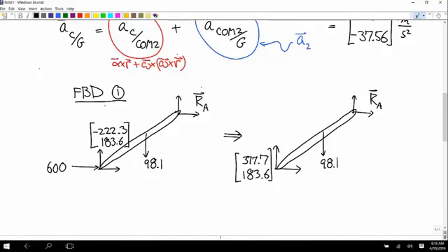I'm not going to do it, but how would you calculate RA if so? Why don't we know that, first of all? How did that not come up in our equations? Because when we isolated body one, we didn't use Newton's second law. That's never part of the steps that we follow. And so we just use the rotational equation, and our about point is at A, and so that doesn't produce any moment. And so that doesn't show up in the equations, even though it's acting on the body. And that'll always be the case for the body with the fixed point.